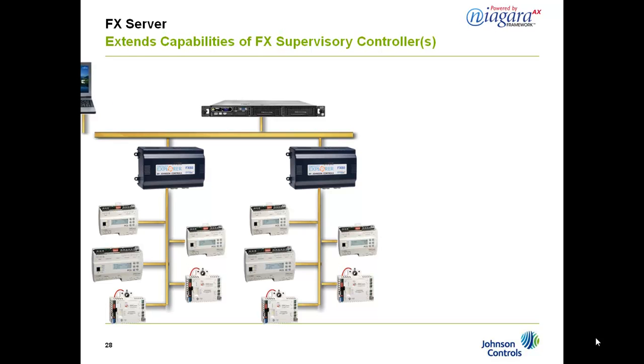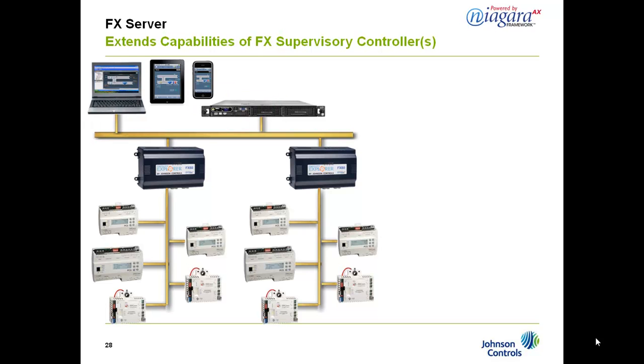And the FX Server can act as a graphics server for the system user interface, either for a single FX supervisory controller, but more often for unifying the system user interface for projects with multiple FX supervisory controllers. Adding FX supervisory controllers and an FX Server to unify them is a powerful way to scale your system upward.